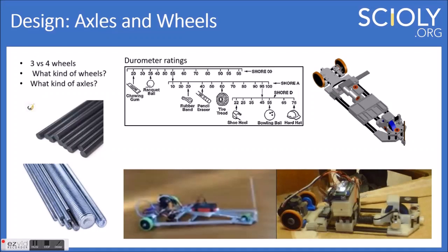They have a very low rotational inertia. They're very light, very strong, very malleable. So you can use them for other things if you need to modify them for whatever reason. And they do fit the ball bearings, those normal, I think they're like 22 millimeter diameter ball bearings. They fit them perfectly, like the standard bearings, which makes it very easy when you're trying to figure out how to construct everything.